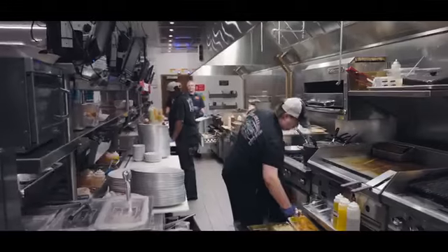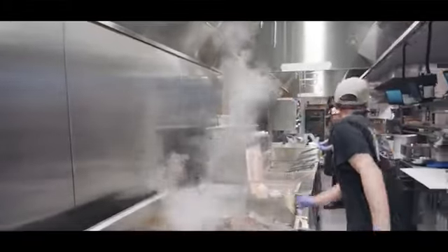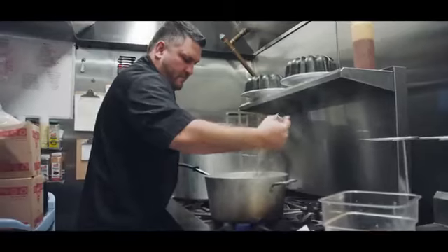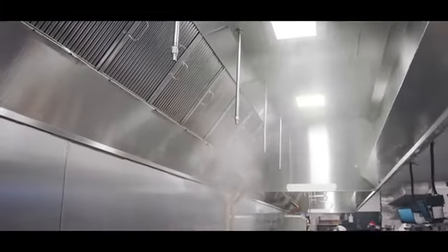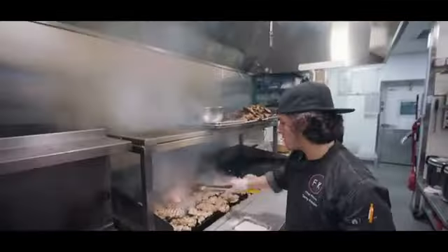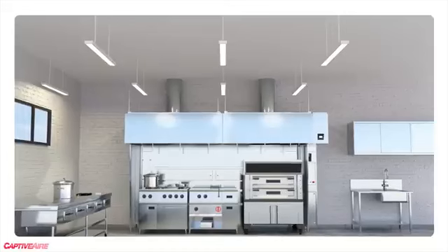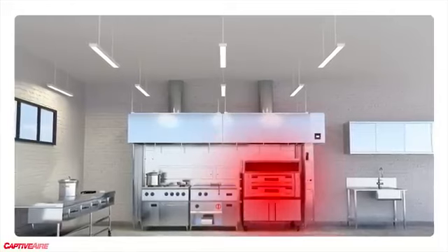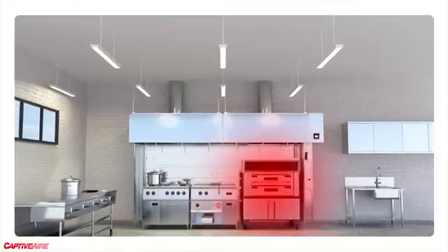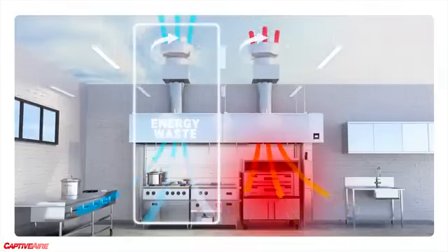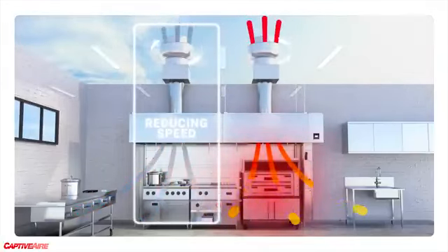We can have a kitchen hood, a very long kitchen hood that has multiple cooking elements, and in this long hood you can have multiple exhaust fans and temperatures associated with each section of the hood. And say one side is just way hotter than the other, why would you want to turn the fan on over here when you're maybe not even cooking? So we can control the fans individually based on their temperature needs.